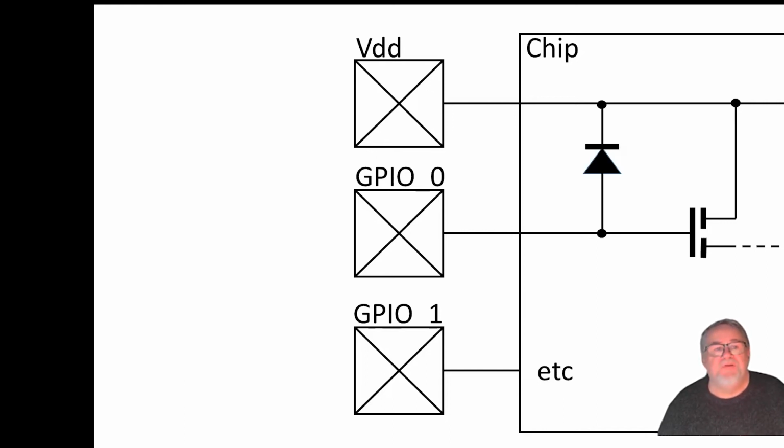So the chip was never getting switched on, except that when he switched it on, there were 5 volts on one of the input pins. And so the 5 volts went through the input pin, up through that diode and powered the chip. And so the chip worked. And it worked away till about 3 or 4 seconds into its initialization sequence, when this input gets switched off. And when the input gets switched off, so did the chip.